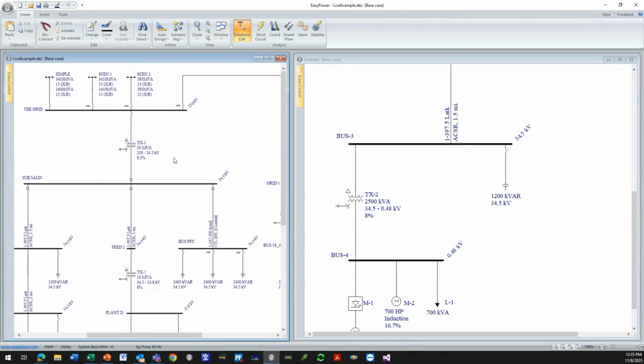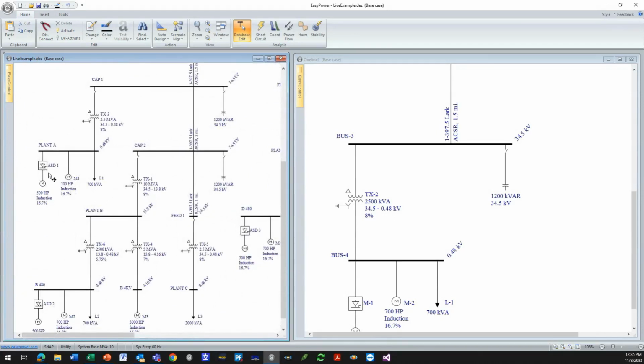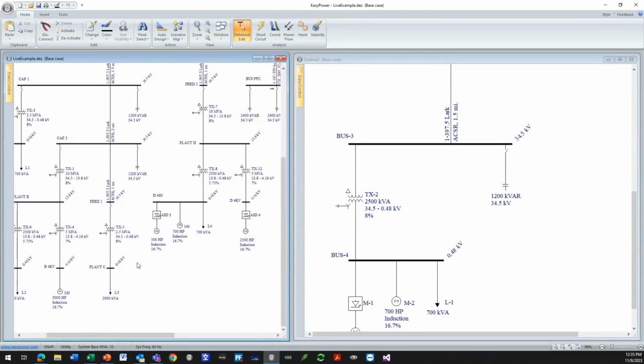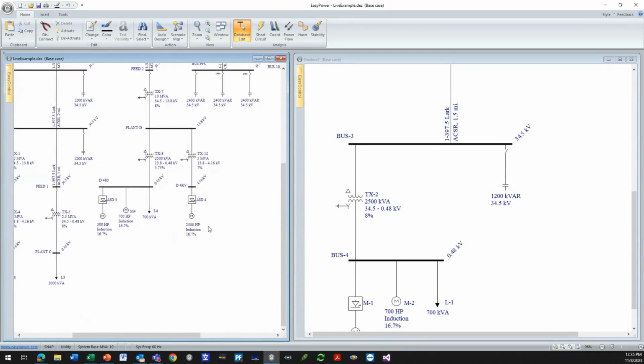And so let's look at the case where I've measured harmonic currents up here. I know that all the drives here, here, and here, over here, are 6 pulse. And I know for certain that this is a 12 pulse drive. I just happen to know my clients in the network.